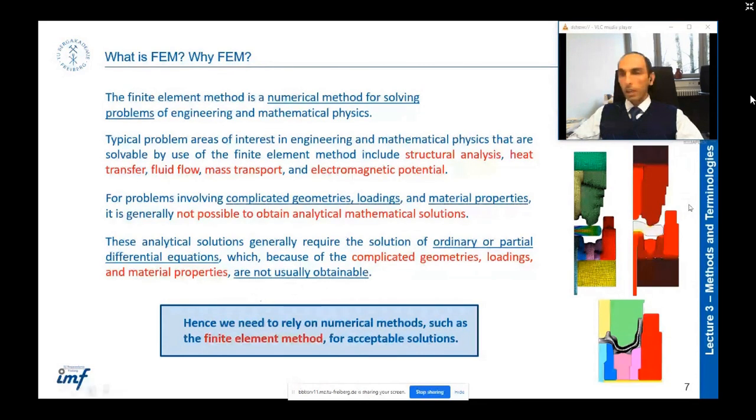Okay, looking at this figure, it's the forging. It's simulating the forging of a flange. Of course, it's just a cross section, and it's axisymmetric, so you should rotate it 360 degrees to see what the real workpiece looks like. However, you can see that the die is very complicated, upper die and lower die, and this figure is predicting the temperature field.